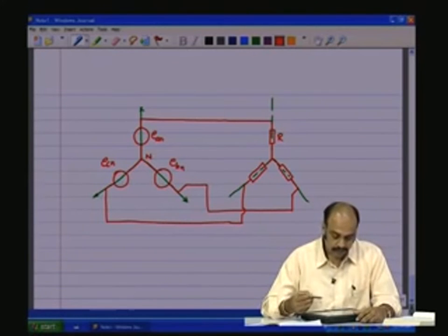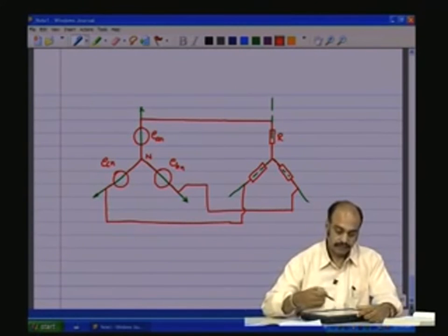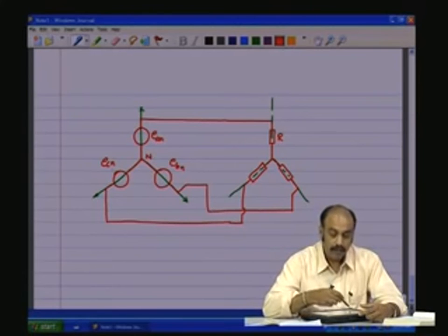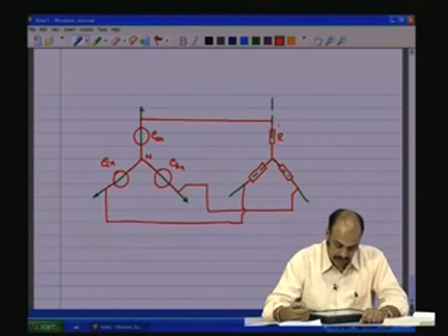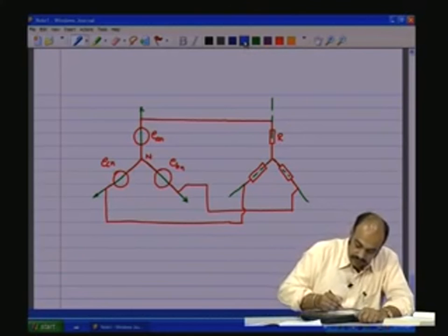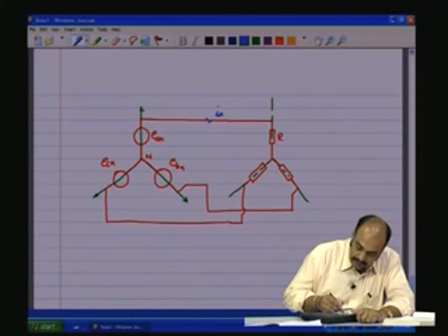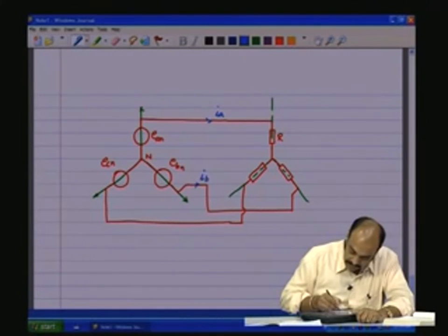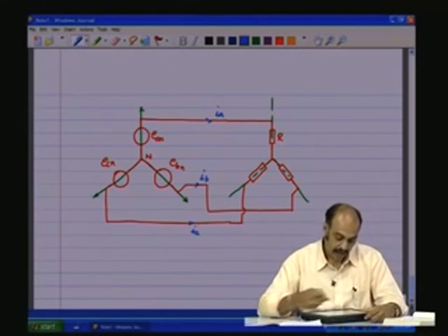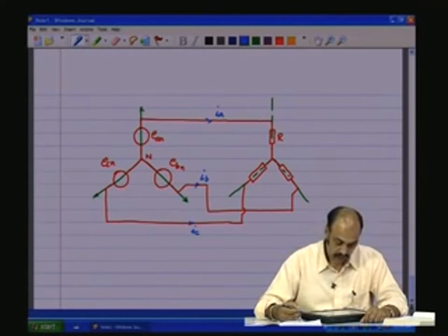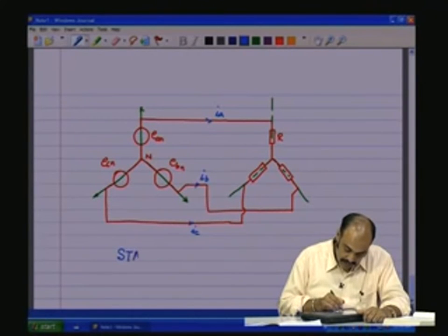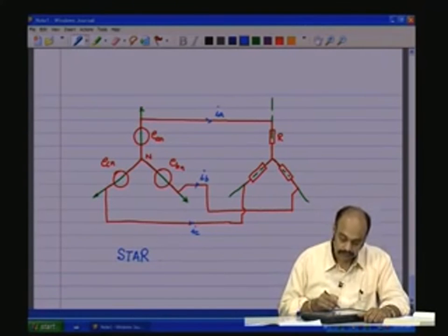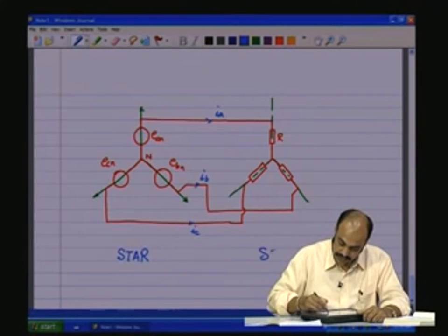So, you see that this is much more aesthetically pleasing and gives an idea that they are all 120 degrees phase shifted with respect to each other in a phasor manner, both the load and the source. So, in the literature you will find this as a pretty common way of expressing 3 phase circuits, and by the way it looks, there are 2 indications. One is that this looks like a star, and sometimes this is called a star circuit. Star load is also in the star form,